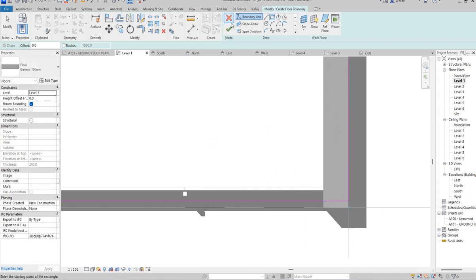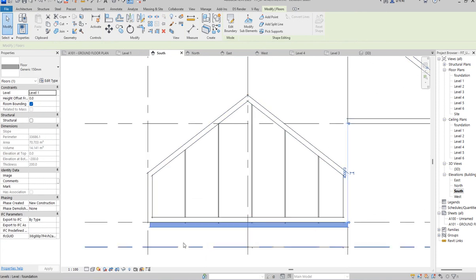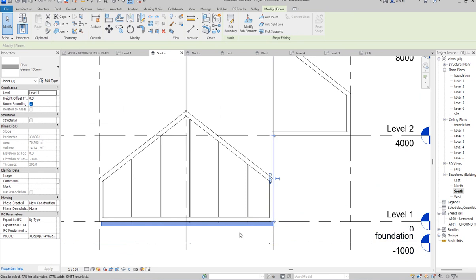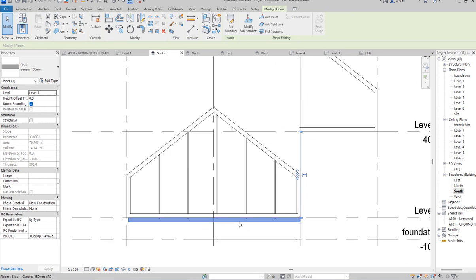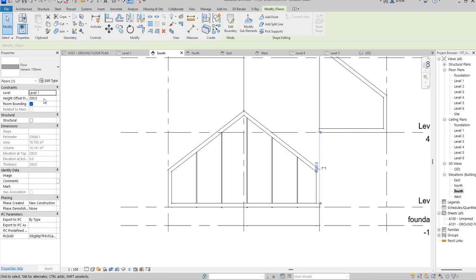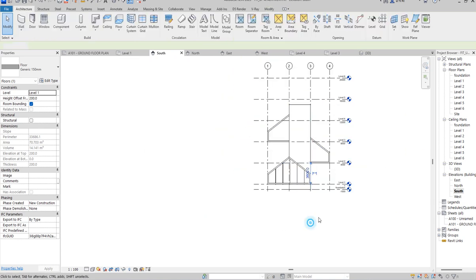Good. So click finish. When you go to the south elevation, the floor is there, but it's below where it's supposed to be. My adjustments can be made to fit in the positions, but I'm not going to do that the way I did the remaining ones, because this one is a different concept entirely. You can just push it up, so it's fixed. From there you can leave it and work with the remaining aspects as time goes. So I have it in place now.